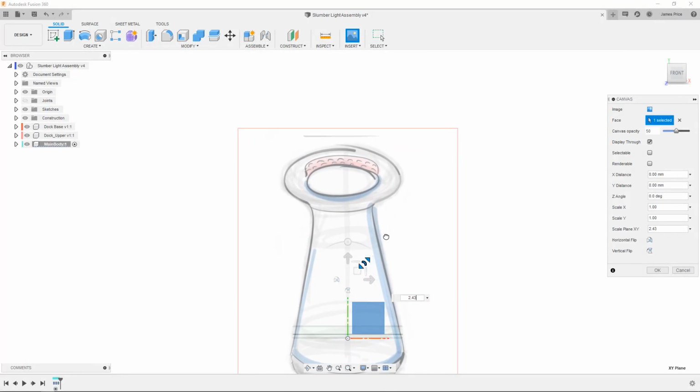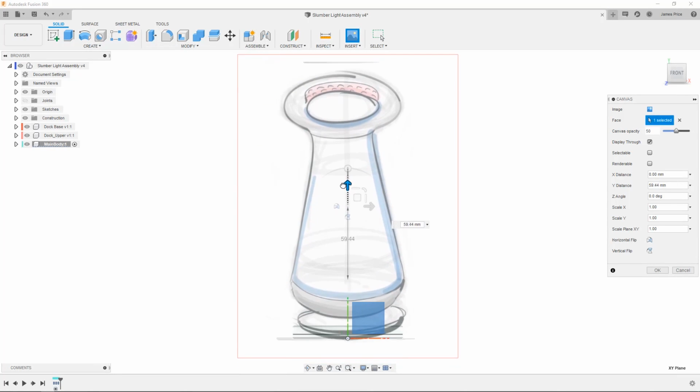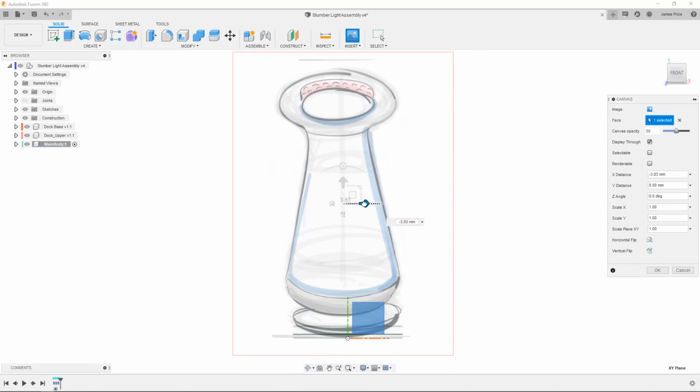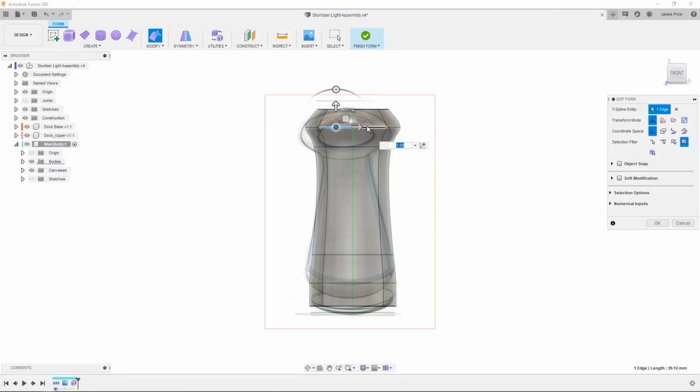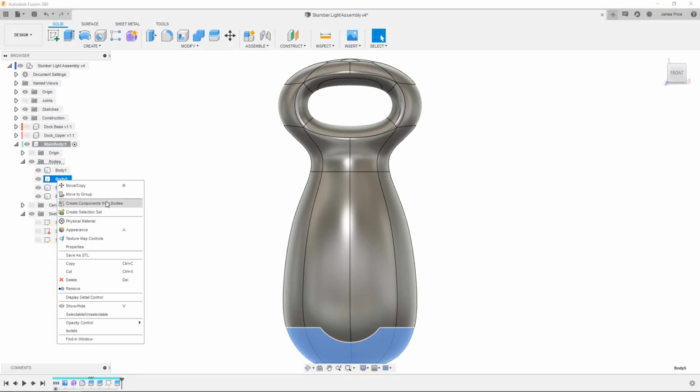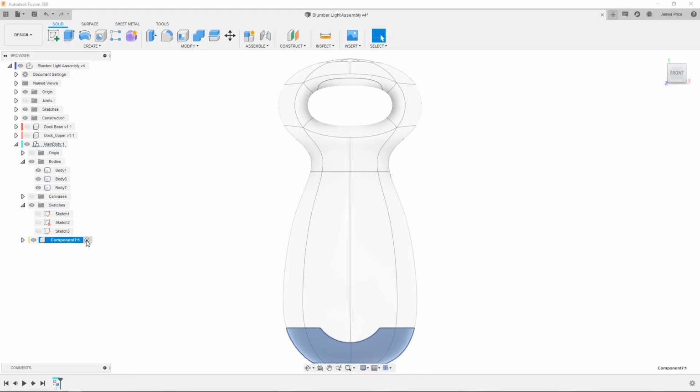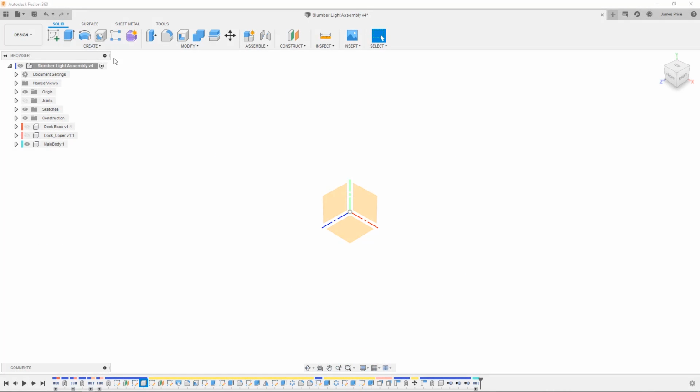Welcome to this next lesson on transitioning from SOLIDWORKS to Fusion 360 surface modelling. To create a freeform surface in SOLIDWORKS, you will typically be used to sketching a set of 2D or 3D splines or profiles, then creating or splitting a surface with these profiles using tools such as lofted or boundary surface. Fusion 360 also has the same surfacing capabilities located under the Surfaces tab, although we call the SOLIDWORKS filled surface command as patch and knitting as stitching.